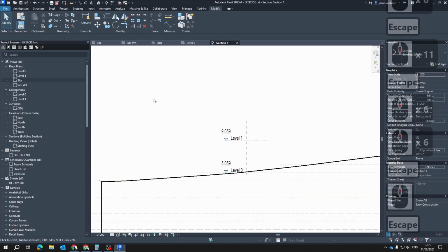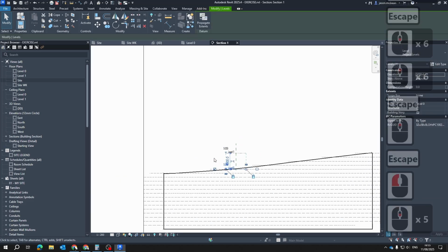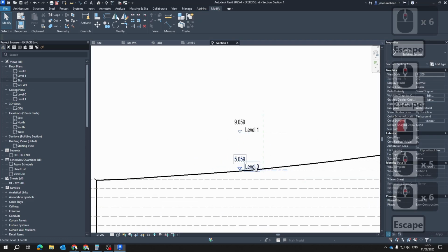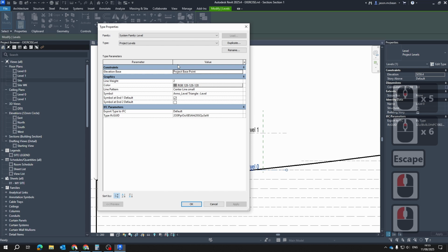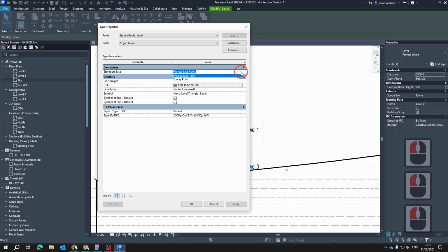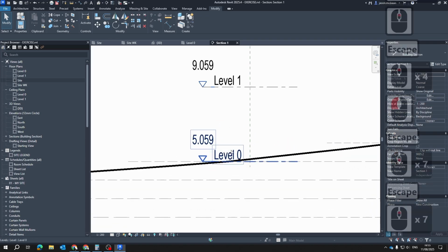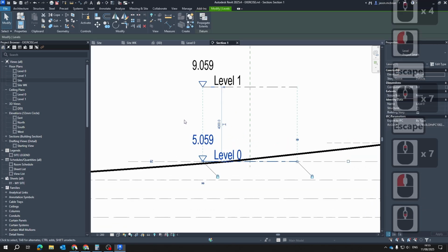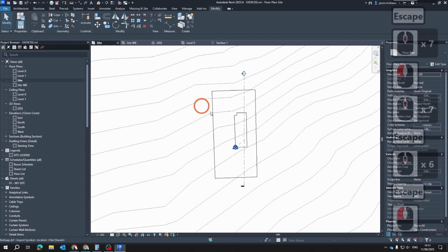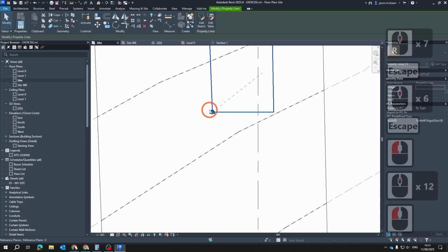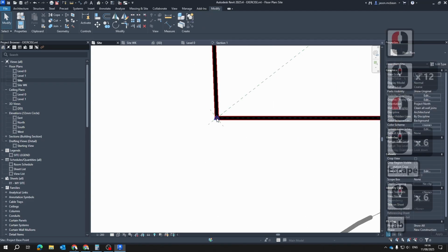But you'll see that this is still showing, so our levels can represent, this is very interesting. You don't have to worry about this too much for now, but you can specify what point. If you want to specify your survey point or base point, let's go to 3D view and reset our project base point back to 0.